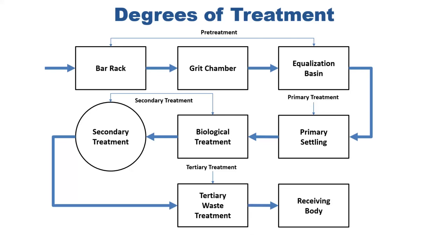The major goal of the primary treatment is to remove from wastewater those pollutants that will either settle or float. Primary treatment will typically remove about 60% of the suspended solids in raw sewage and 35% of the BOD5. Soluble pollutants are not removed. At one time, this was the only treatment used by many cities. Although primary treatment alone is no longer acceptable, it is frequently used as the first treatment step in a secondary treatment system.